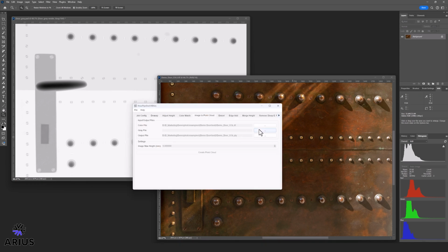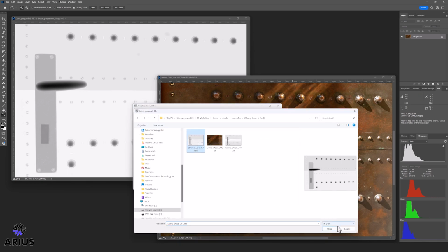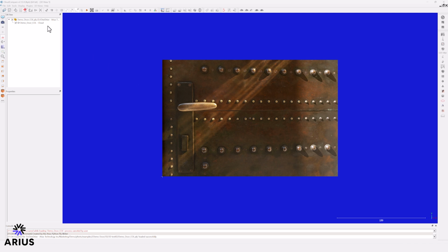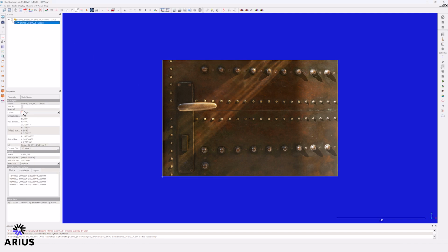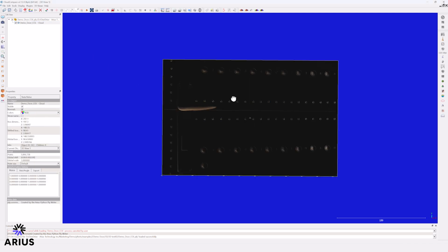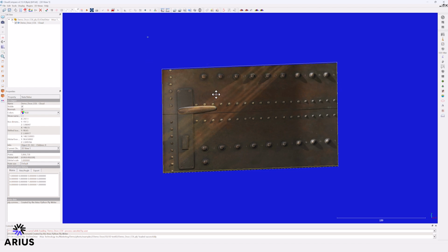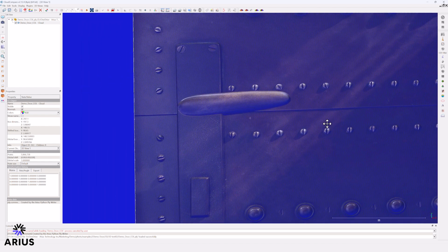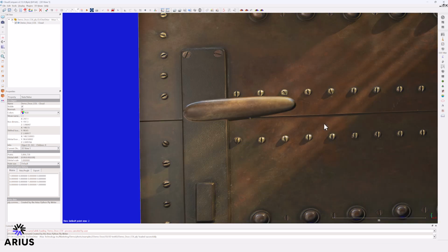Using these, generate a point cloud preview with the image to point cloud converter to see how the process is working. Load the resulting PLY file into Cloud Compare and consider the results. Zoom in with the mouse wheel, and then adjust the point size by holding Alt and the mouse wheel, until the flat areas appear solid.